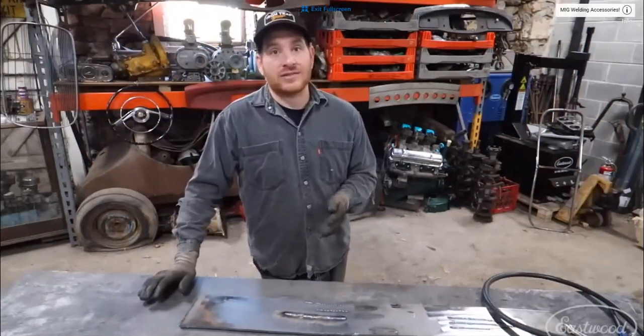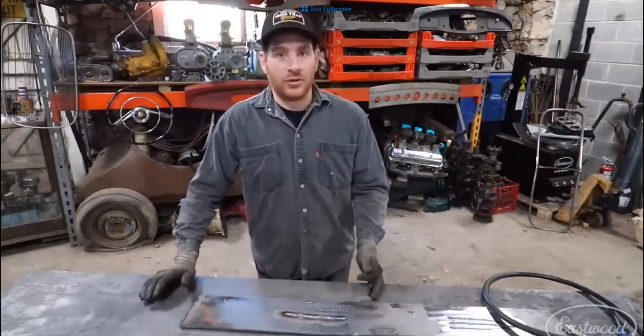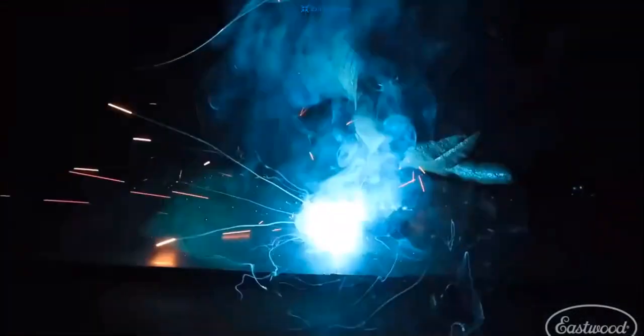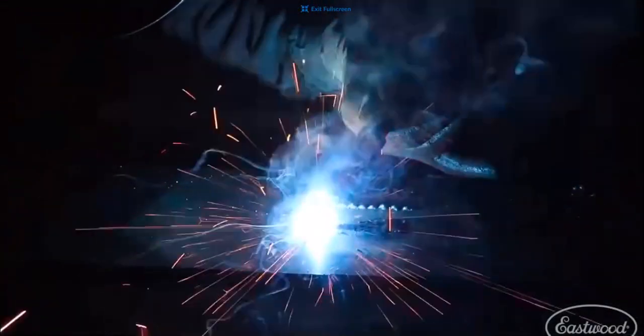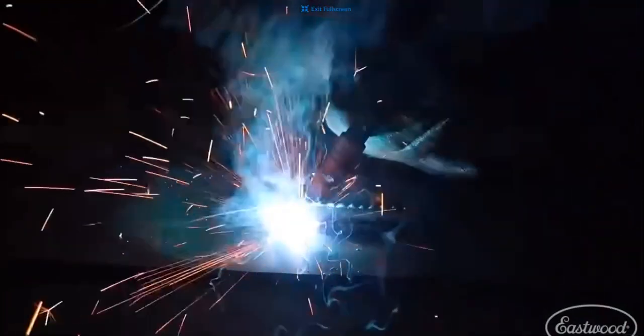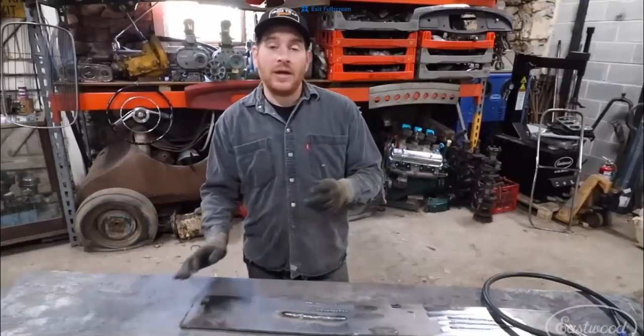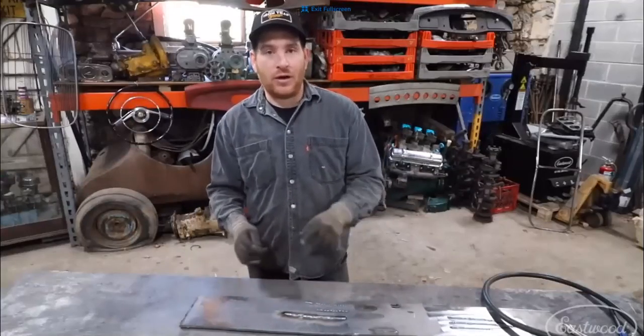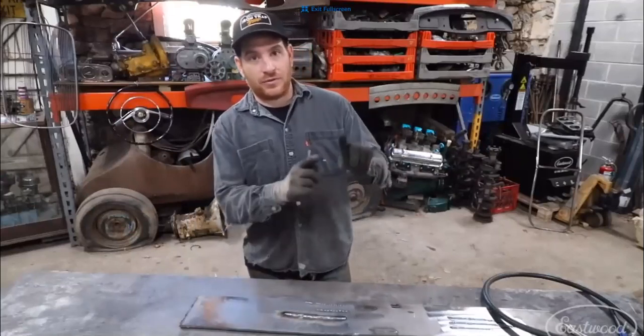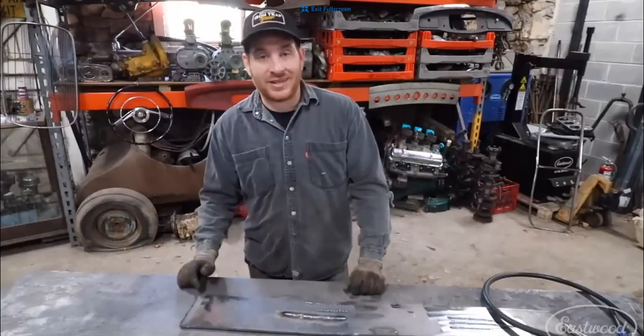The other thing that can cause that is a technique issue. If you have your wire stick out too far, or you lift your hand while you're welding, or you start too high from the panel, you may have too much stick out and it's actually dropping the power. Even though you may have the machine cranking all the way up, you may be dropping the power of the weld because it's causing more resistance to jump across that long piece of wire that's sticking out there.